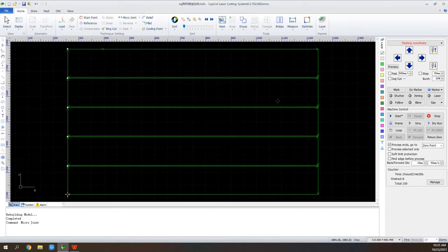We've got manual and automatic micro joints, 2 ways. Click the icon and add joints to where we want, or choose the automatically generate the micro joints. Press Shift on the keyboard and click the micro joints, we can clear them if we don't want it.